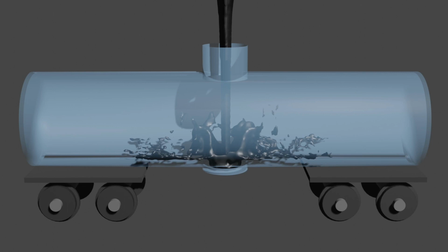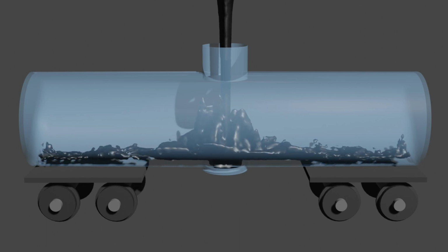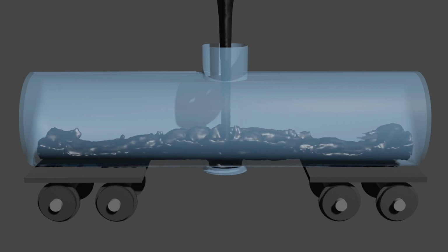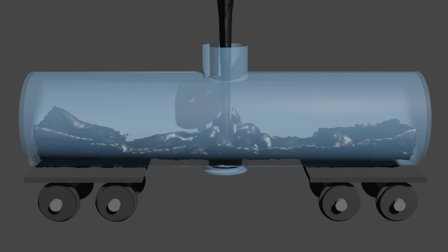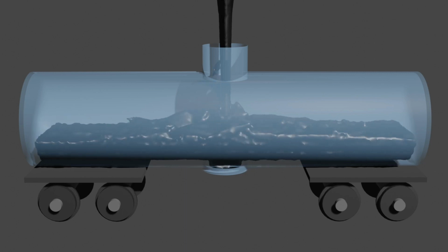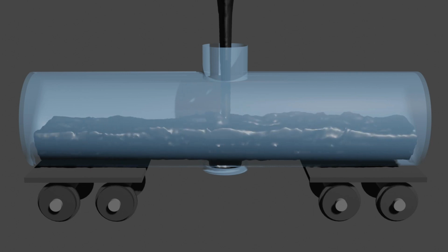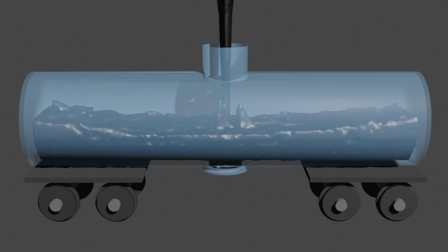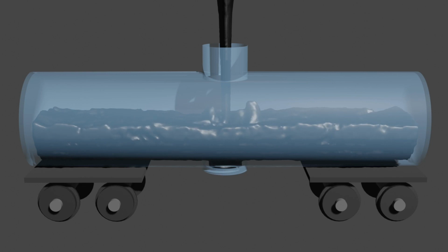However, when the crude is added to the car, the scavenger is mixed directly with the incoming crude. In this case, there has likely been reasonably good contact, so the H2S content has also likely been reduced. Do keep in mind the time component of the reaction, and testing immediately after filling may provide an inaccurate result.